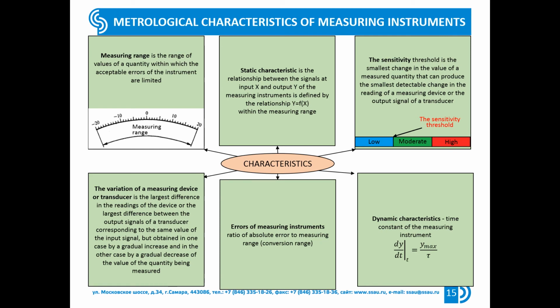Measuring instruments are assigned accuracy classes, the notation of which coincides with the percent value of the reduced permissible basic error. Accuracy class K is denoted by a number from the following series: K equals 1, 1.5, 2, 3, 4, 5, 6, multiplied by 10 to the power n, where n equals 1, 0, -1, -2, etc.